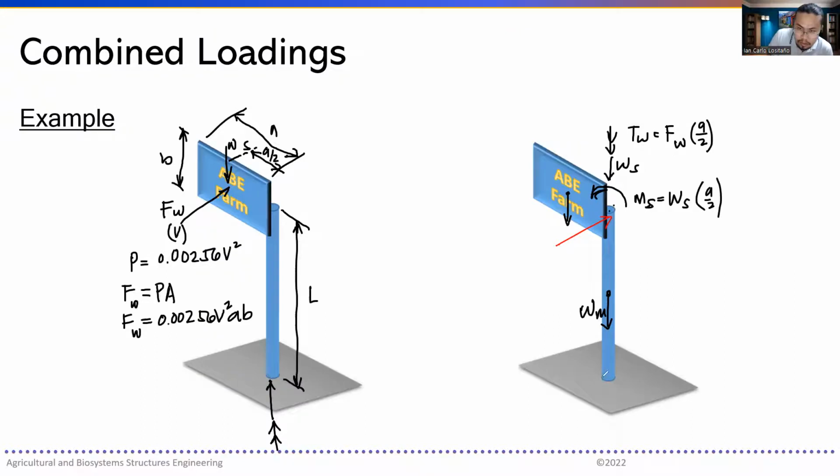All right, so now on to the bottom, or the reaction at the bottom. This would have a reaction again, as drawn a while ago, and then a torsional force, that's T. And then we have here a V, and then we also have here an M1, and another M2 is expected to be a moment. That's going to be expected over there on the other side. Again, this is going to be along this plane. So those dimensions. Right, so that's the solution to this one.